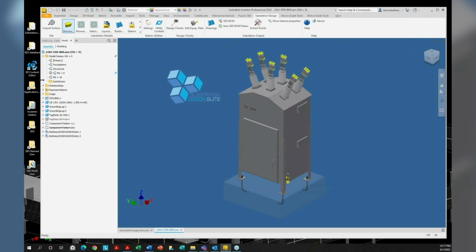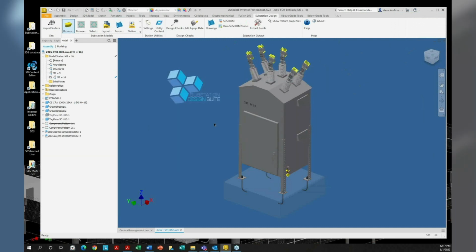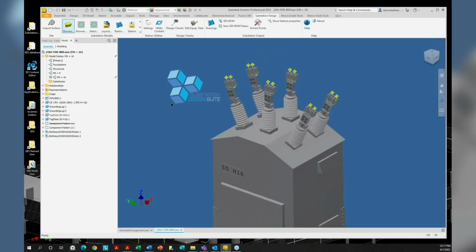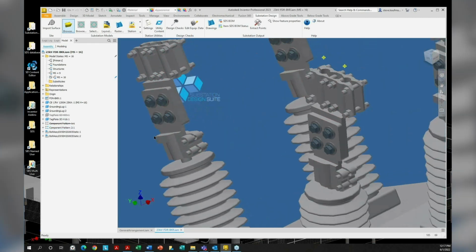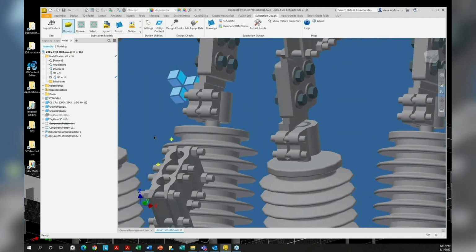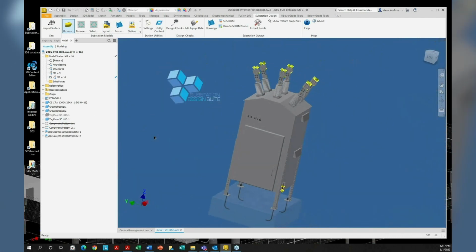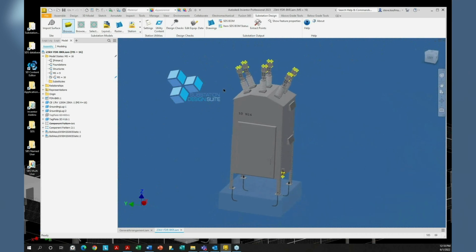So when I'm changing this, I'm going 16 to 19, right? If you look at what's going on here, I have a component pattern for the fittings. And these fittings all have their hardware attached to the fittings, and I'm changing it with them. In this case, I did not add a parameter to change the height.